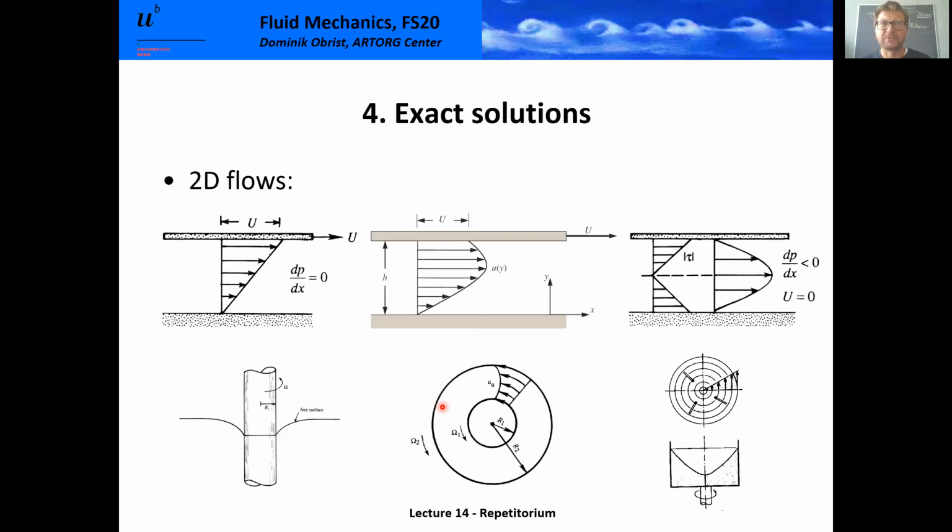It's a bit of a mishap that these two words, vortex and vorticity, sound almost the same, but there are vortices without vorticity. And it's exactly that vortex, which is called an ideal vortex, which later on we learned is also a potential flow solution, a vortex without vorticity. Okay, so these are some of the results that we obtained in the lecture on exact solutions.